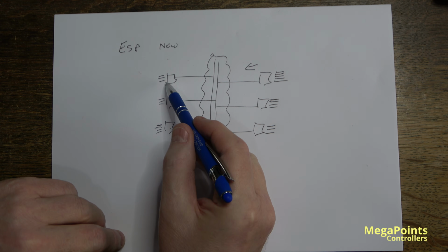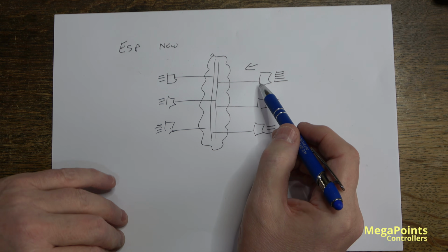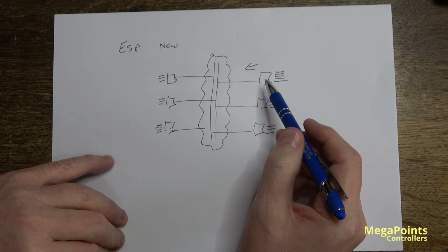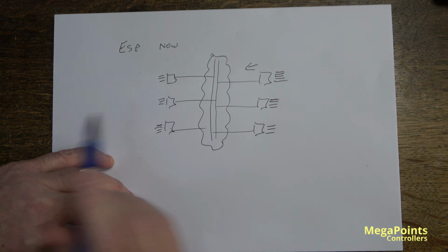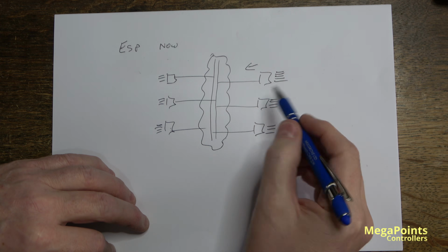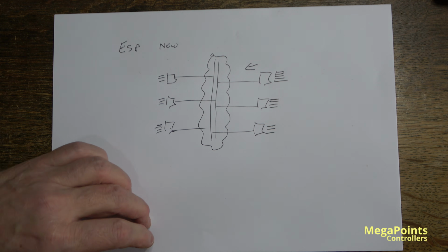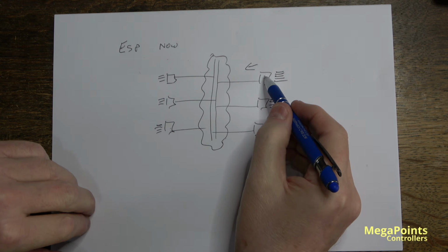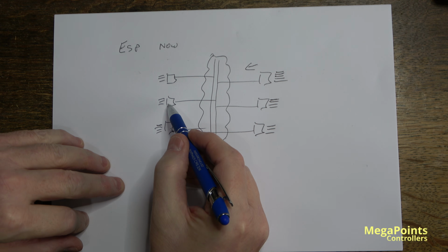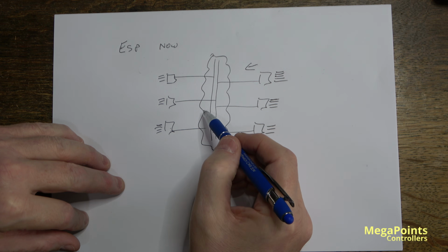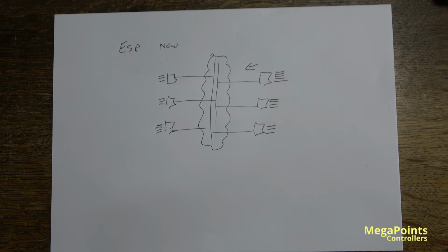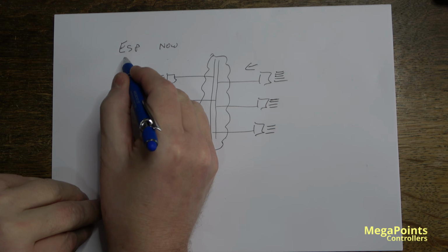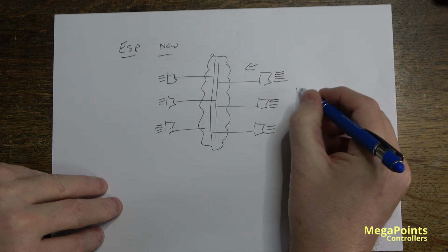So we're sending data here and we're getting an acknowledgement back. If we don't get an acknowledgement back, then it's up to us as the application developers to then go, okay, nothing happened in an agreed time frame, retransmit it. So we're taking care of how to transmit data and get it to wherever it needs to go. So if this board sends the data here, this board has to acknowledge it, even if it's not intended. It's sent a message, it has to say acknowledge or go through this timeout loop. So it's expensive.